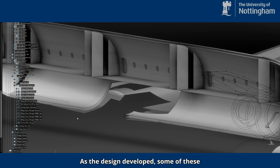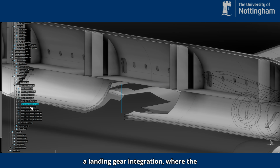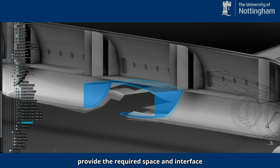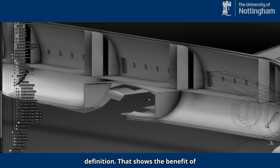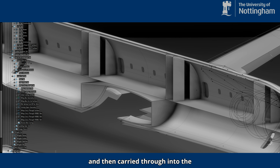As the design developed, some of these references were refined in response to downstream requirements. One example was landing gear integration, where the initial geometry was later adjusted to provide the required space and interface definition. That shows the benefit of using a top-down approach, as changes could be pushed back into the skeleton and then carried through into the independent geometry.